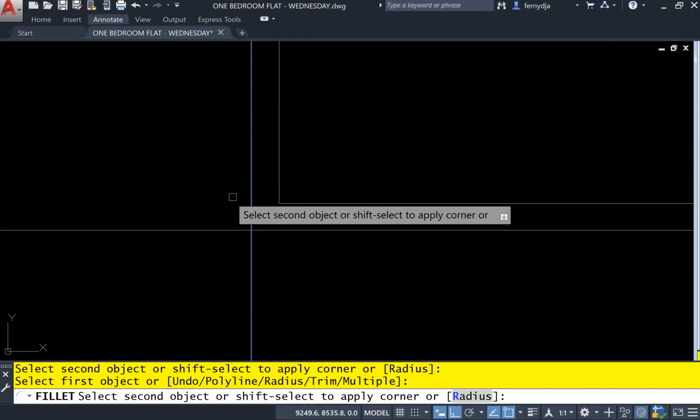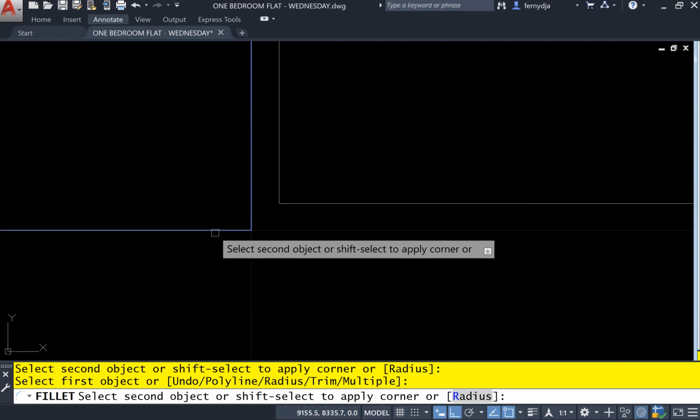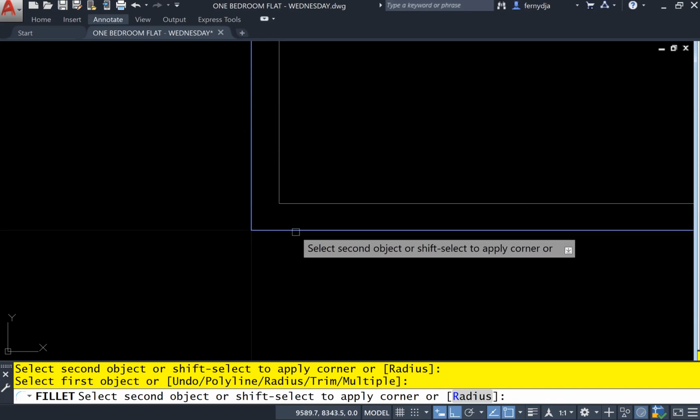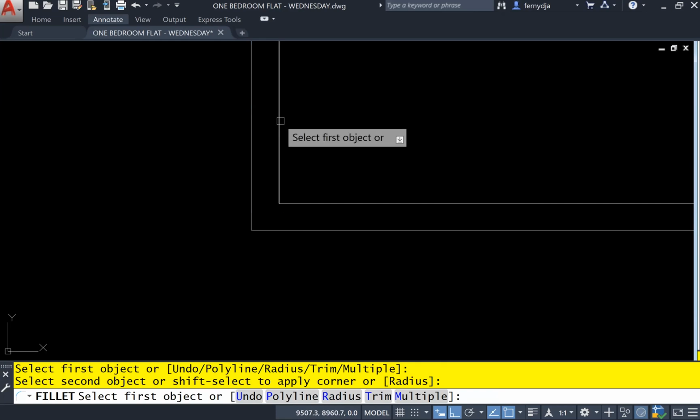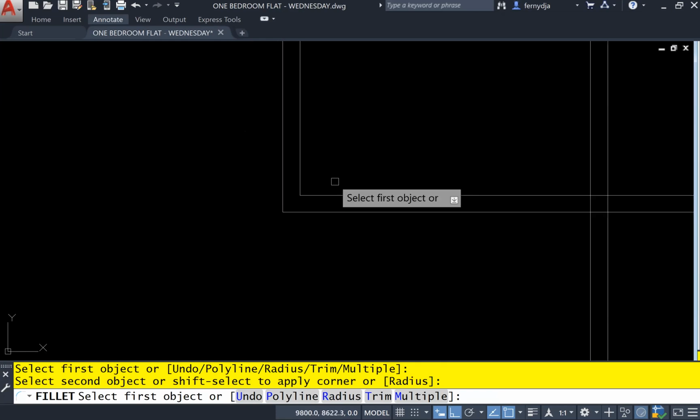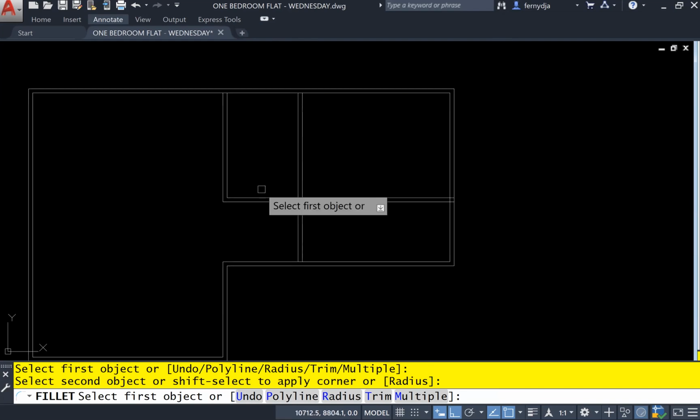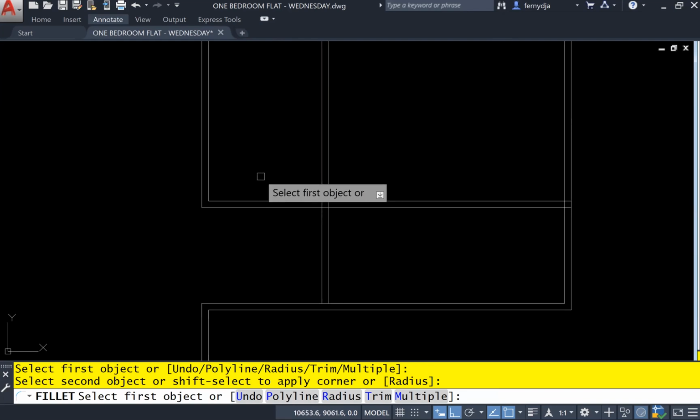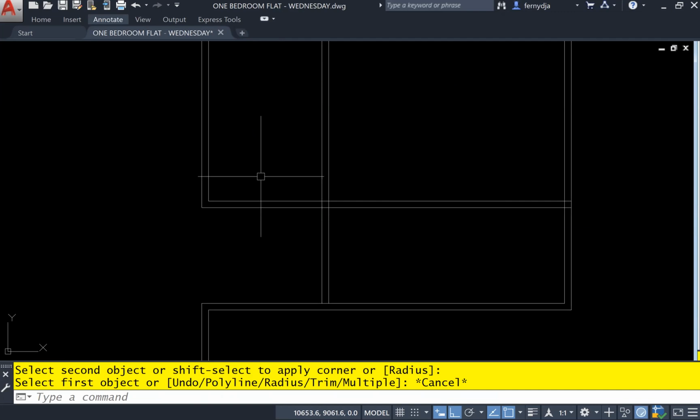And if you go over here, you'll see what would have happened. So you know it can't be on that side. So it will be on the other side, right? So it's the two portions. So we click the two inner and the two outer lines. And if you notice, we now have an L-shaped corner. So I'm going to press escape to finish that.